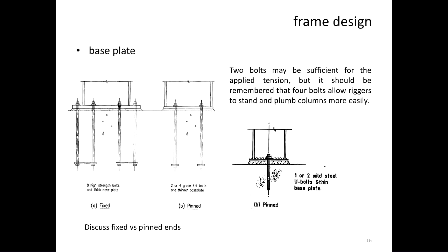Now, when that is placed, that is been set, you put that, and then you concrete the footing, and then later on you put your column over, and that column, as you can see, does not sit directly on the footings. Why? Why do you think that is the case? Tolerance, yes, you allow tolerance.